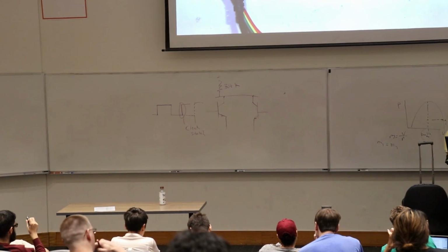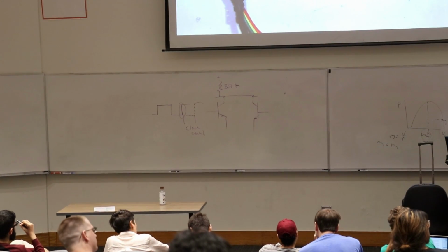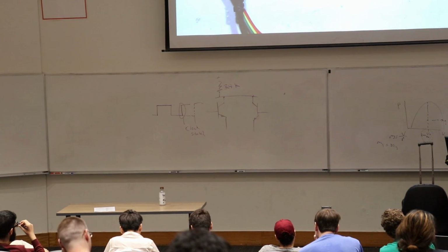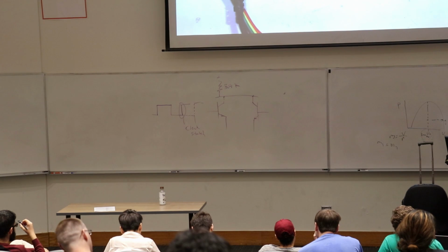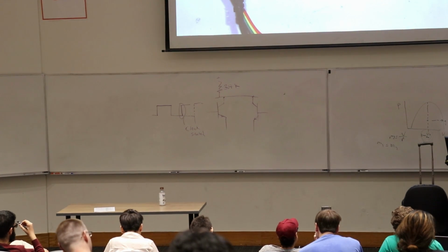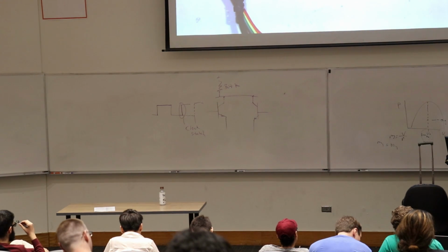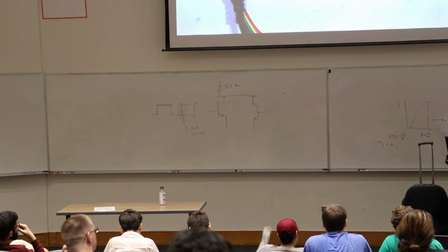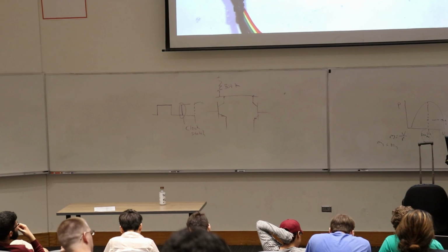Well, if another master starts transmitting at exactly the same time, then there could be a problem, right? The way they detect that problem is every time they send out a high bit, they check to see if the bit goes high. If the bit doesn't go high, they know that something else is holding the data line low. It must be another master. So they back off and let that master take the bus and run with it.